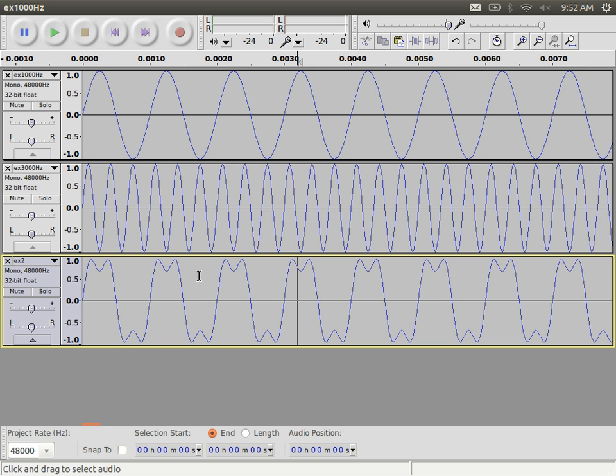Yep. How to get frequency A? Okay, the question, it's a good question, is, okay, we know the component frequencies, 1 and 2. If signal A is made up of components where the component signals are integer multiples of 1, which it is, that is, if we have a fundamental frequency, then the frequency of A is the fundamental frequency. So it's the same in this case. So it's 1000 hertz. And hence, the period of A is also 1 millisecond.